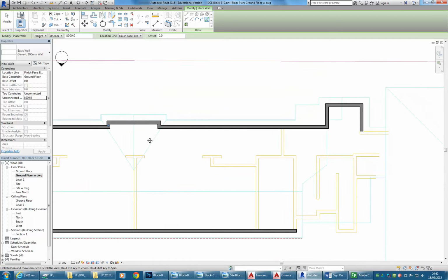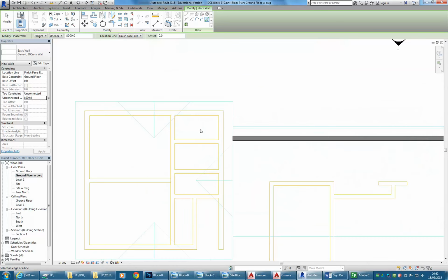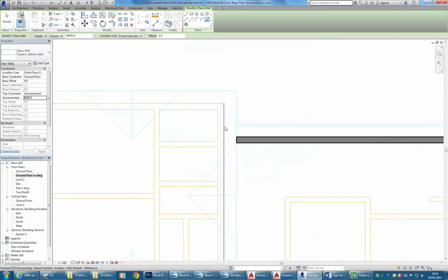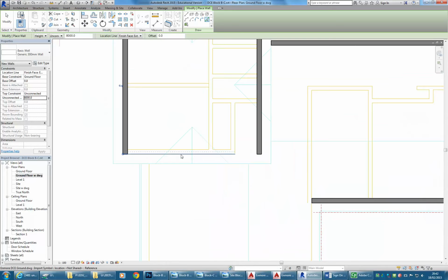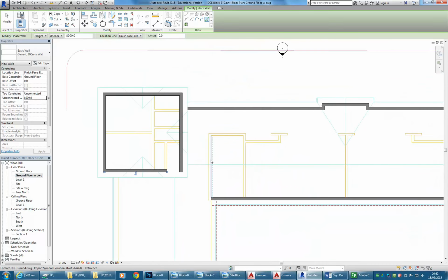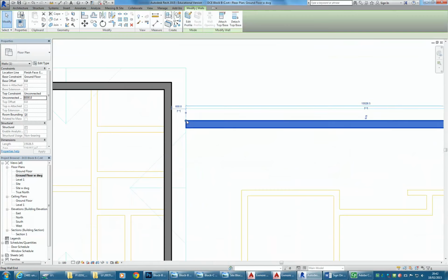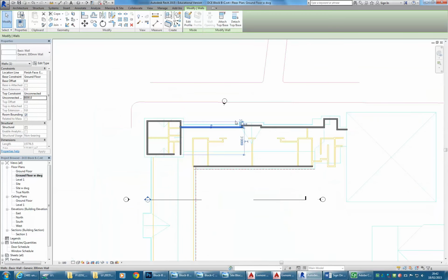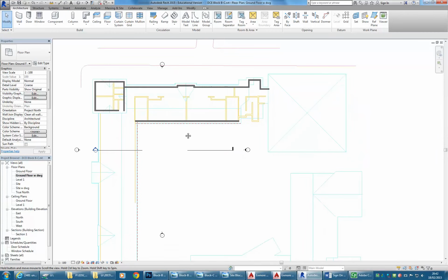Hopefully you can see once you've done the work in AutoCAD, it's pretty quick then to get it knocked up in Revit from those lines. So you're not drawing it twice really, especially if you use things like pick lines. It doesn't take very long to get that all converted to walls. So I might go through the internal walls next week, but that's plenty to get you started.